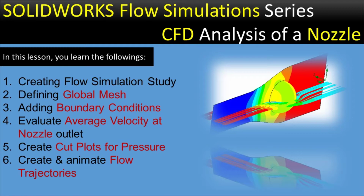Today we are going to perform CFD analysis of a nozzle using Solidworks Flow Simulation. In this tutorial, you will learn how to create a flow simulation study using the Solidworks Flow Simulation wizard, and you will also learn how to create a global mesh and control it, add velocity boundary conditions, similarly pressure boundary conditions at the outlet of the nozzle, and evaluate average velocity at the nozzle outlet. And you will also learn how to create cut plots for pressure and how to create and animate flow trajectories along with cut plots or surface plots.